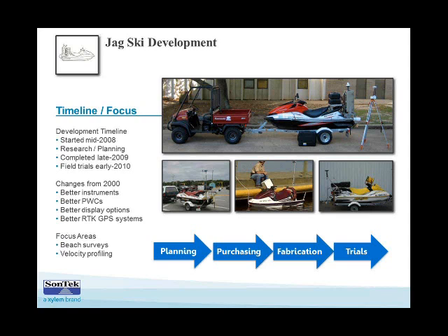But I've found that I'd rather sacrifice the top 20 centimeters of the water column for what I do, and get really good, strong quality data that's not bouncing off the hull. So really, our depth is limited by how deep we mount the ADCP, but I've surveyed in about 30 centimeters of water. Half a meter of water is a little bit more realistic of a goal. Of course, if you're willing to put the ADCP right at the surface, where only the heads need to be wet, as long as they're continuously wet, you could get into much shallower water.